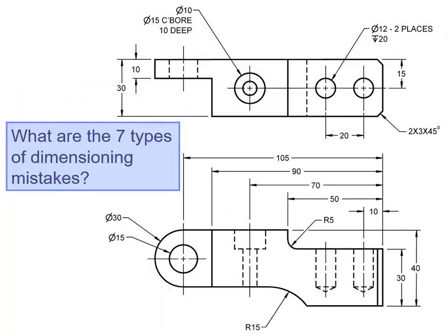Next slide. Let's practice our drafting again, how to place and call out dimensions, or how to correctly label dimensions and use symbols. Right off the bat, we can see that we should avoid using words. Again, this was acceptable 50, 40, 60 years ago, but in the last few decades, we got away from using words. Instead of counterbore, we'll use the U shape to define a counterbored hole. So here we have a counterbored hole. And for the depth, instead of using the word, we're going to use the downward arrow.